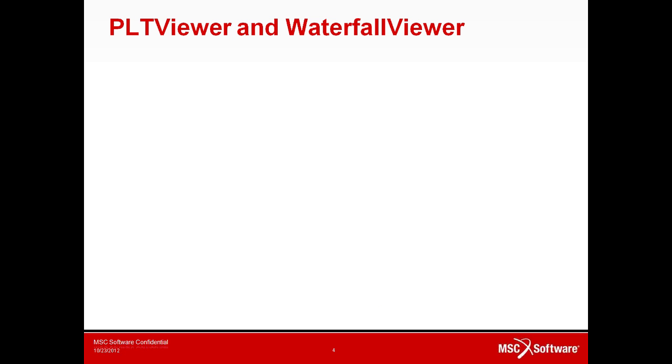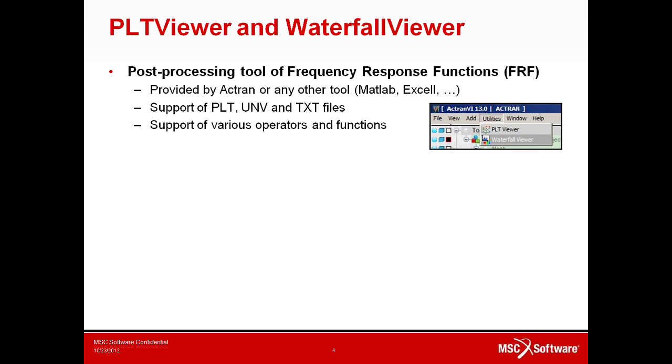The PLTViewer and the WaterfallViewer are dedicated tools for post-processing frequency response functions, or FRF in short. These are accessible from Actran VI and are part of the Actran VI module. Both tools can import different result formats, including external data provided by other tools, such as MATLAB or Excel, to combine different results into a common visualization.